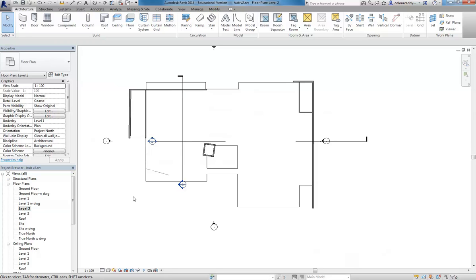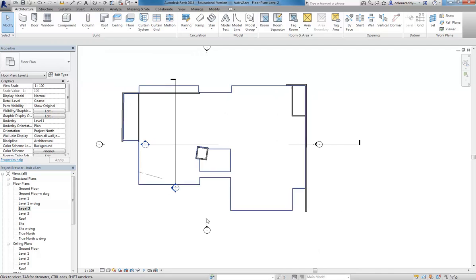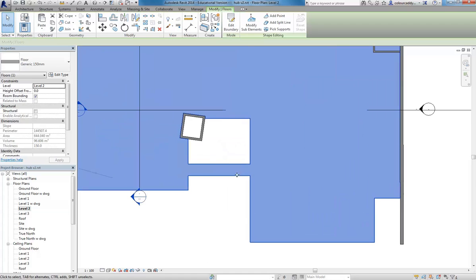So, I mean, floors are pretty straightforward usually, as long as you don't try and do anything too fiddly with them. And, oh yeah, maybe with walkways and balconies, you can see I've just done it all as one floor, so it's all at the same height. And from a design point of view, that's often a good way of doing it, because people like that transition between the indoors and the outdoors without having to step down. But it still can be good practice to have that step down floor level for your outdoor areas.